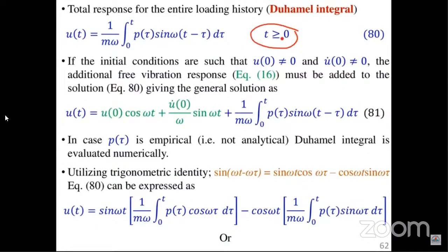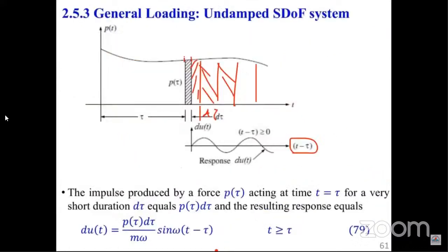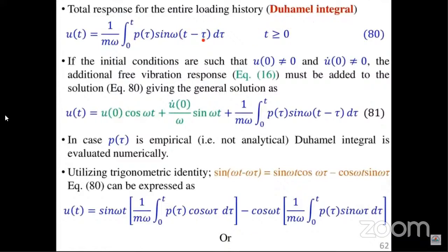But we know, of course, that the time when the force is experienced is when t is greater than tau. And that's why in our expression, we have this time t, the negation of this part. So even in our integral, although we are integrating from the time t equals 0 up to the edge of the loading period that we are considering here, we know, because of this part here, that our motion will only experience the externally applied force, or the forcing function, when t exceeds tau.